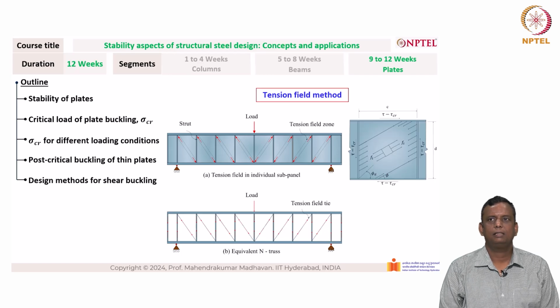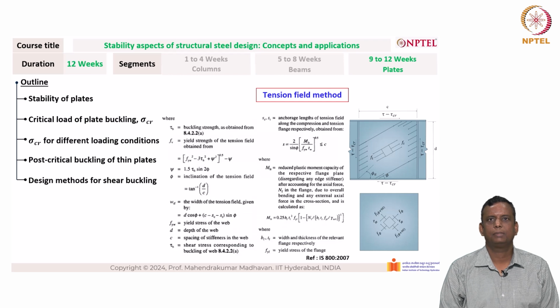The theoretical derivation behind the tension field action will also be discussed in this course. As you can see from the right hand side, this shows how the principal stresses are acting. On one side it is tension, on the other side it is compression. The derivation will lead to the tension field method that is given in IS 800, as you can see here.